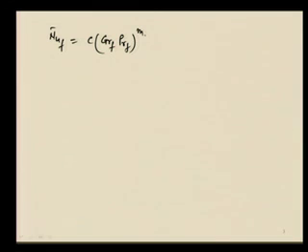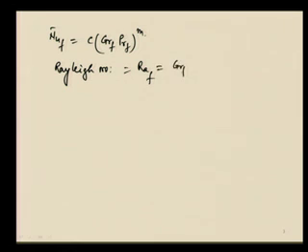Now, here one thing, as I told you, in the table it is written as Rayleigh. Here I have written Grashof into Prandtl. Actually, this Rayleigh number is nothing but written as Ra_f, where f just indicates that the properties are evaluated at film temperature, and this is equal to basically Gr_f into Pr_f.